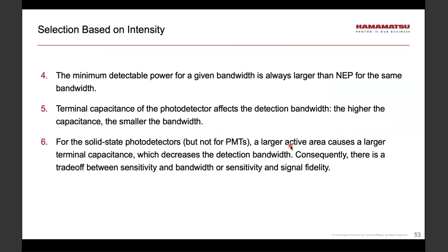Another important point to make is that signal to noise ratio will depend on bandwidth, detection bandwidth. And so it is crucial that the user uses only the amount of bandwidth that is necessary for that particular detection. Too much bandwidth will only add noise to the detection, and too small bandwidth may diminish the fidelity and the size of the signal. So one has to be careful about this particular parameter.